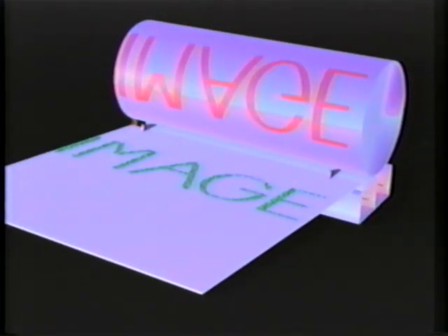After transfer, paper and photoconductor move over the separation corona. This corona wire is supplied with an AC voltage. It produces an oscillating electrical field which breaks the attraction between photoconductor and paper. With the force of attraction neutralized, the paper's own stiffness usually separates it from the photoconductor, though curled or unusually thin paper may continue to stick. Pick-off pawls provide a mechanical backup for electrical separation. These small, sharp fingers ride against the photoconductor and strip off any paper not separated by the corona.